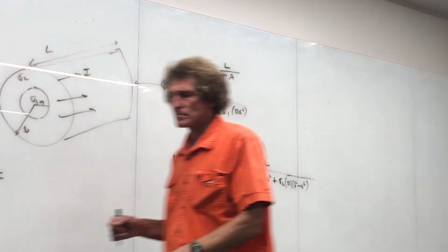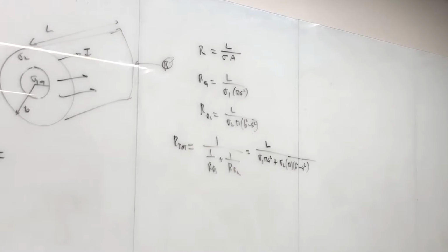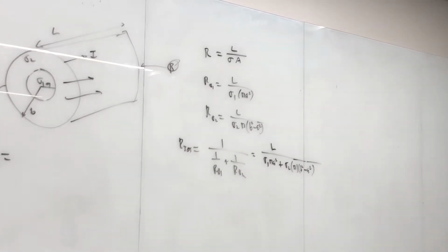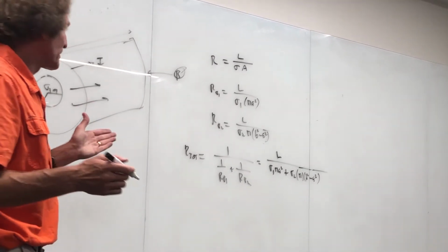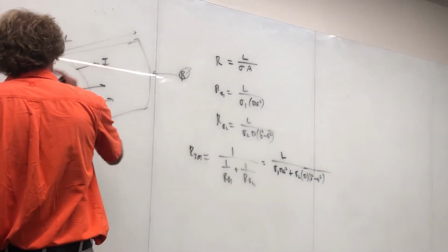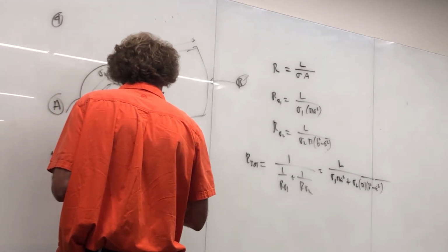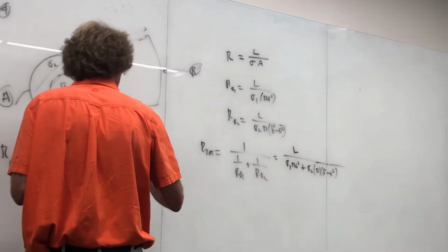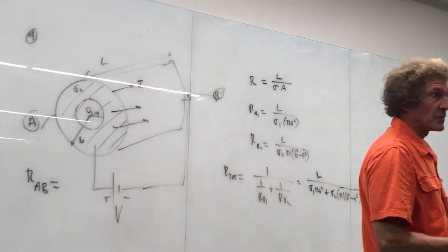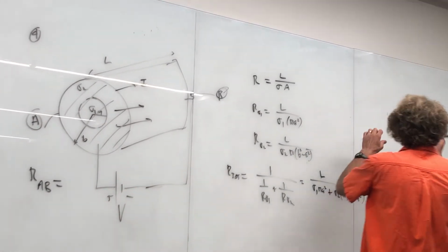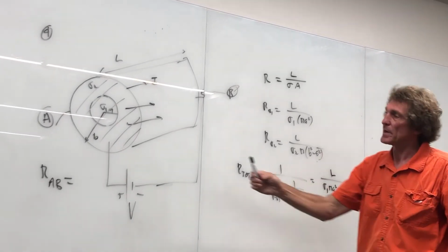I gave you that formula, and that's what I was looking for. I'll show you the other way to do it. Actually there are several, but I'll just tell you one other way. Suppose this whole surface is metallized and you put a battery here, with plus to minus, say V, going to this side. Here's how you would do it if you assume the voltage between the plates. You start with V, then you get E. E would be constant through here.